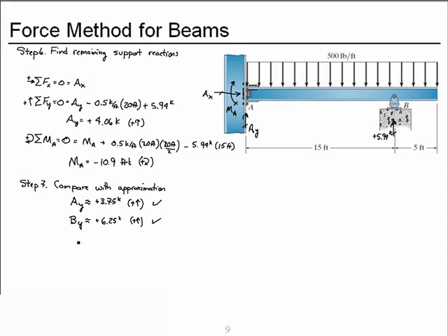Those are reasonably close. And we said that the upper limit on the moment at A would be a minus 25 foot kips, so not clockwise but instead counterclockwise. And we obtained a not clockwise, therefore counterclockwise answer of about minus 11.